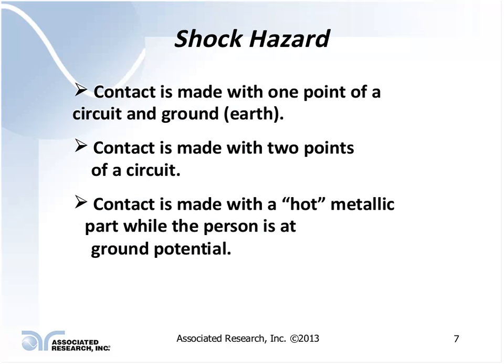Electrical shock. Whenever a person receives an electrical shock, it is usually because they themselves have contacted one point of a circuit that is energized and they themselves are grounded, because all of our power systems typically are ground referenced.